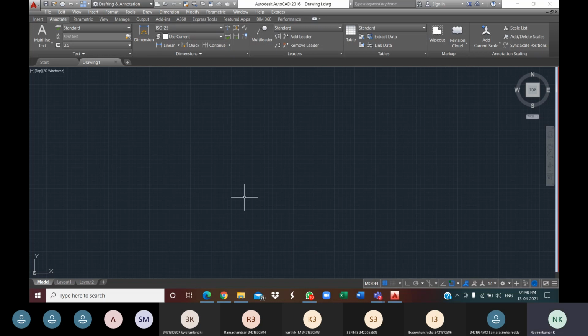it will be opened like this. After that, if you start the drawing, this screen will open. Then it depends upon the requirement. If you want the grid like this, you can leave it. If you don't want the grid, see here, Display Grid: if you click on this, it will be off. Then if you need the grid again, turn it on and the grid will appear on this screen. The grid will be of some distance, 1 centimeter or 2 centimeters, in one scale.